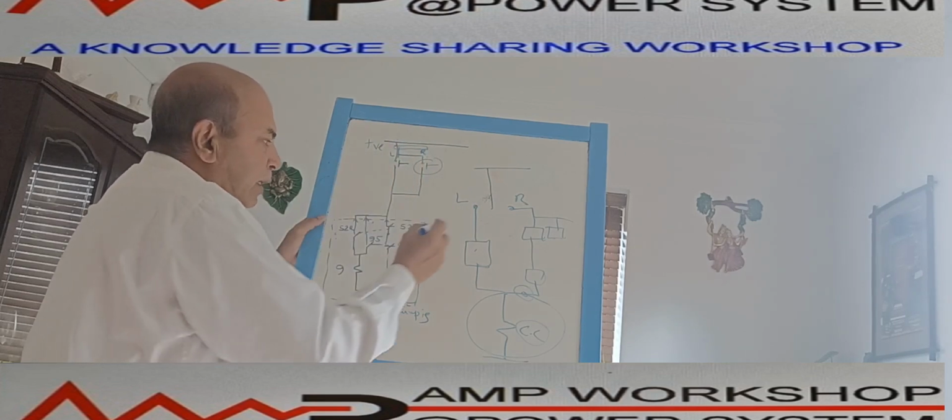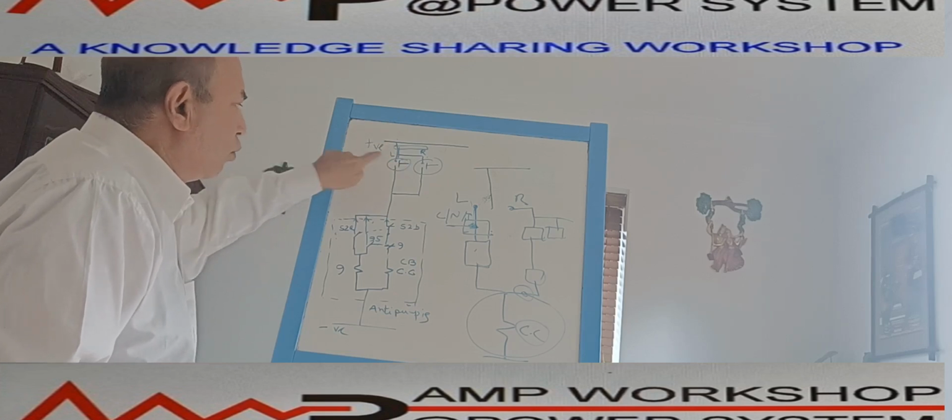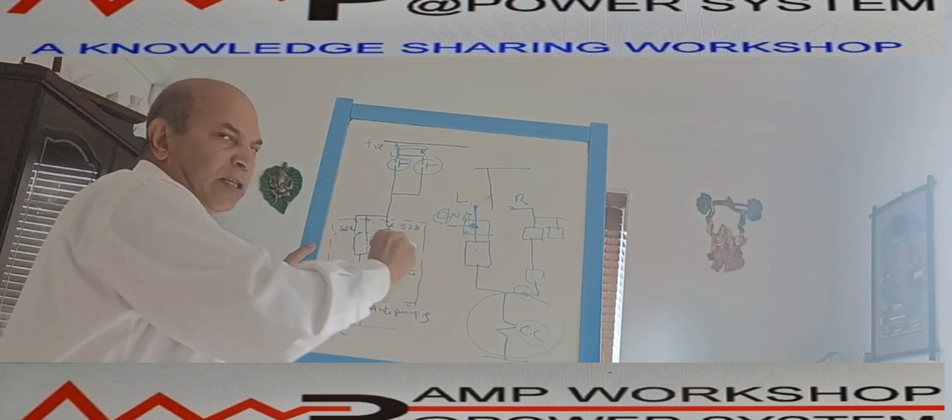Suppose this is the local position, then here is your local closing. After selecting local, you have a close, neutral, trip switch. Here is one switch, which I have shown for simplification as a push button. So this is a closing push button. It is a part of this selector switch: when I put it in the close position, the breaker will close, and when I put it in the trip position, it will go to the tripping circuit. So this is a closing command. After the closing command, there is the interlock over here, the disconnector interlock. Then it goes to the closing coil as before.